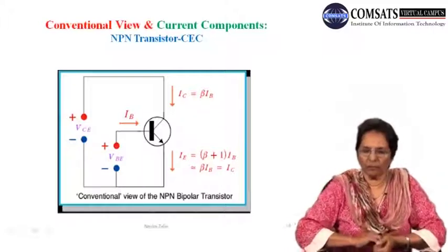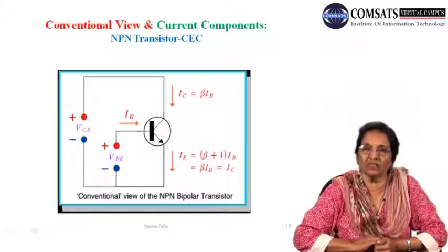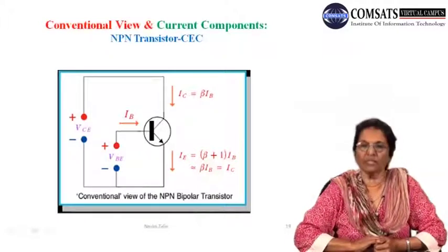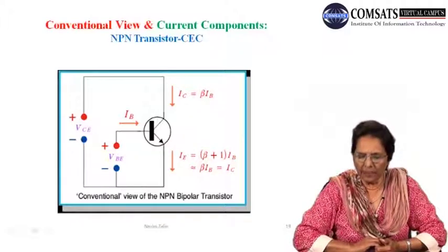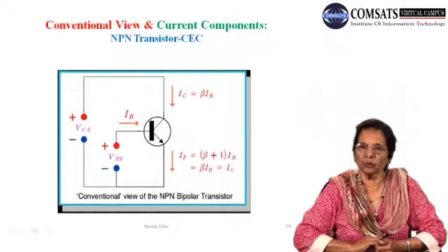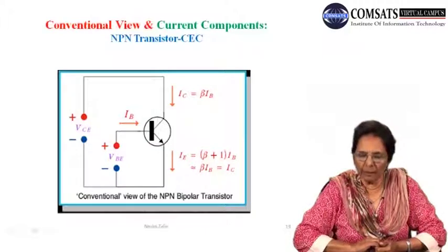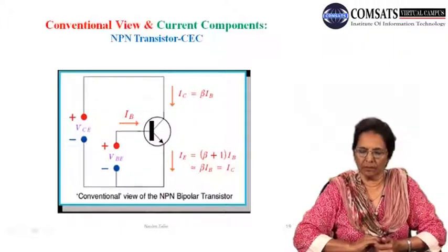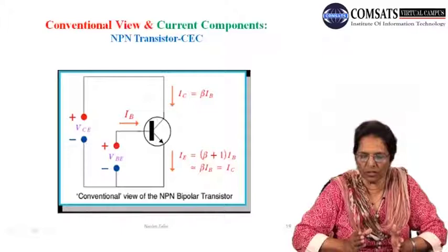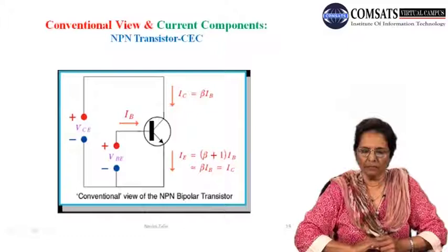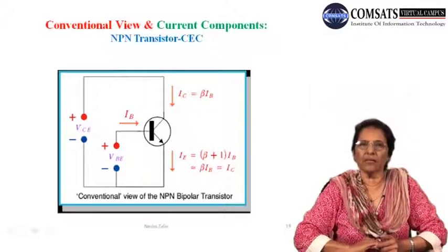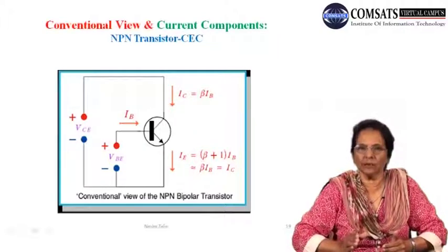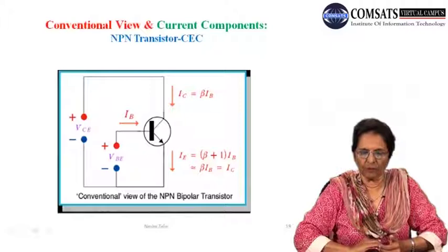तो जस्ट बाय लुकिंग at the arrowhead we can tell that this is an NPN transistor operating in the base emitter junction obviously would be forward bias. तो चूंकि ये NPN transistor है, the base would be positive, is connected with the positive terminal of the battery, and for an NPN transistor, the N-type emitter is connected with the negative terminal of the battery.